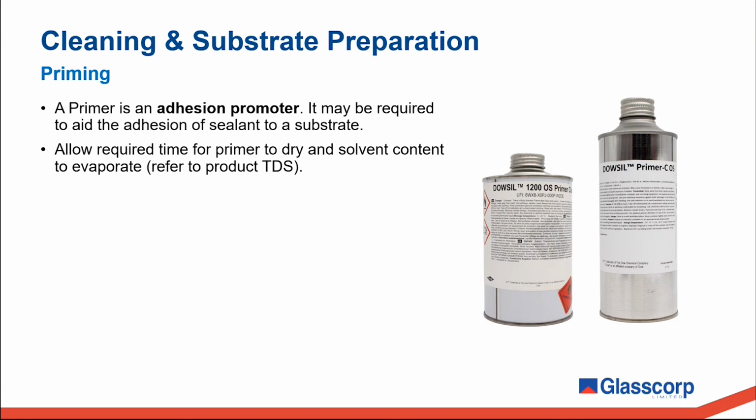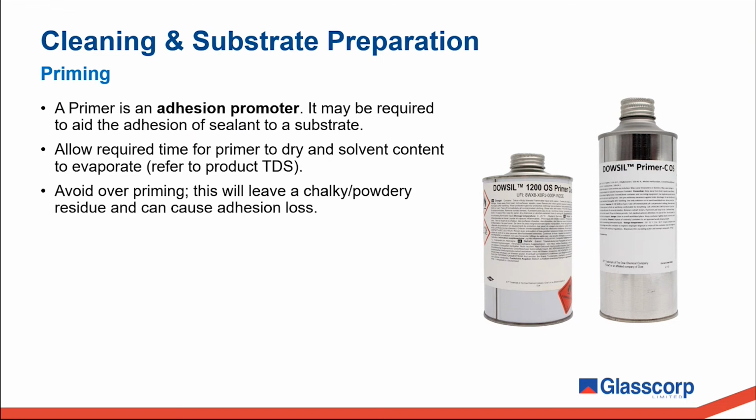Primers should be applied according to the instructions set out in the product TDS. So make sure you allow the required time for the primer to dry and the solvent content to evaporate before applying the sealant. While you need to allow the required time before applying sealant, you also need to make sure that you're not leaving primed surfaces exposed for too long either, as there is a risk of surface contamination.